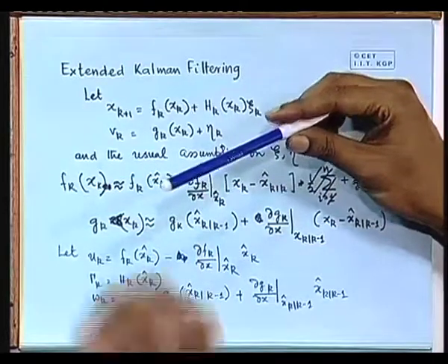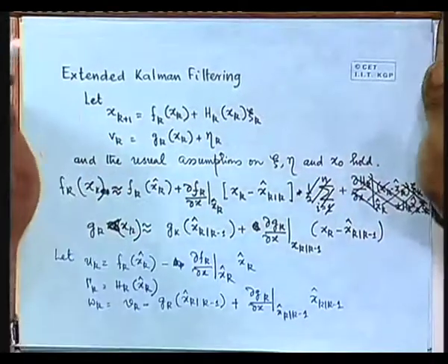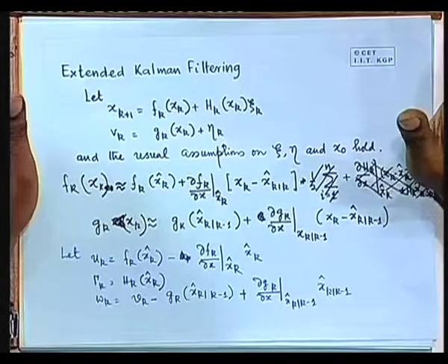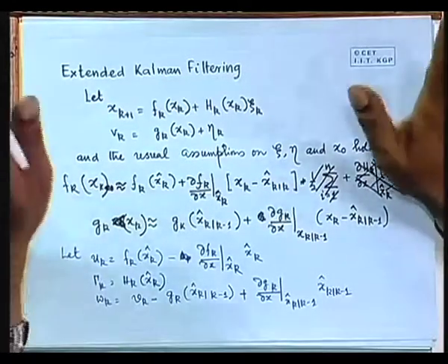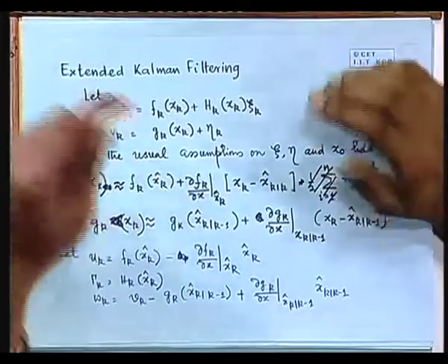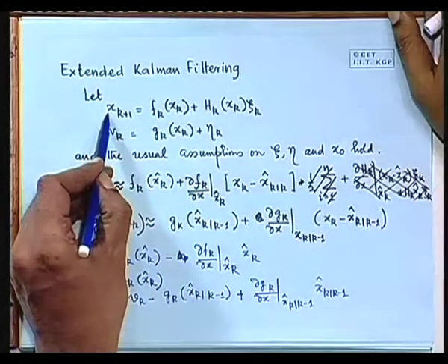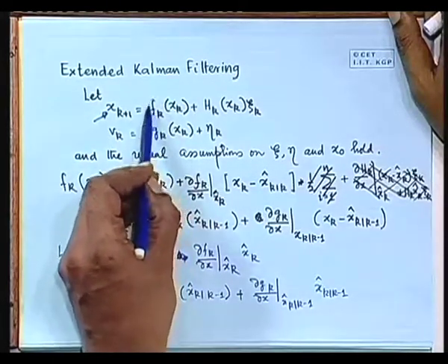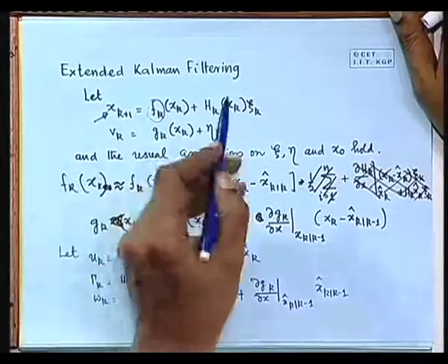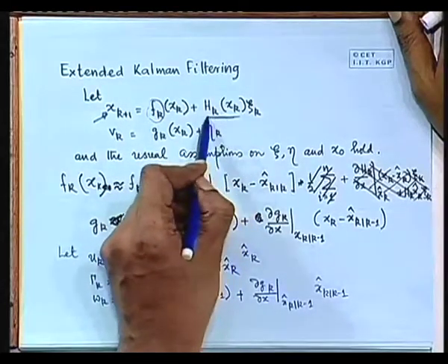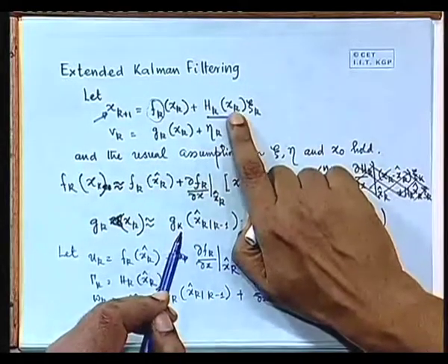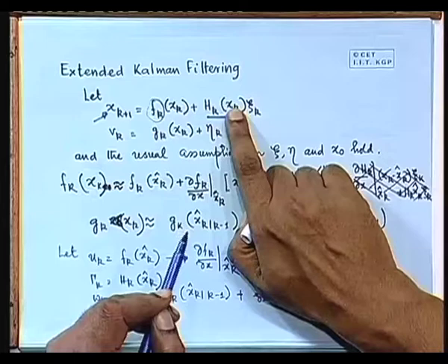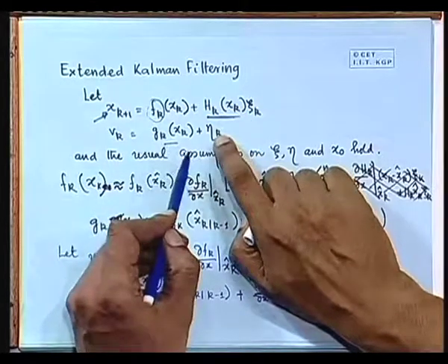So you see that there is a simple formulation available by which you can do an approximate Kalman filtering for a linearized model of a nonlinear system. So at least you can do something. So we are assuming now that we have a nonlinear system given like this. This is now not a matrix but a vector function, a nonlinear function. You see that the B matrix is now a function of x, so it itself is nonlinear. Similarly this is nonlinear, and this is the measurement noise.